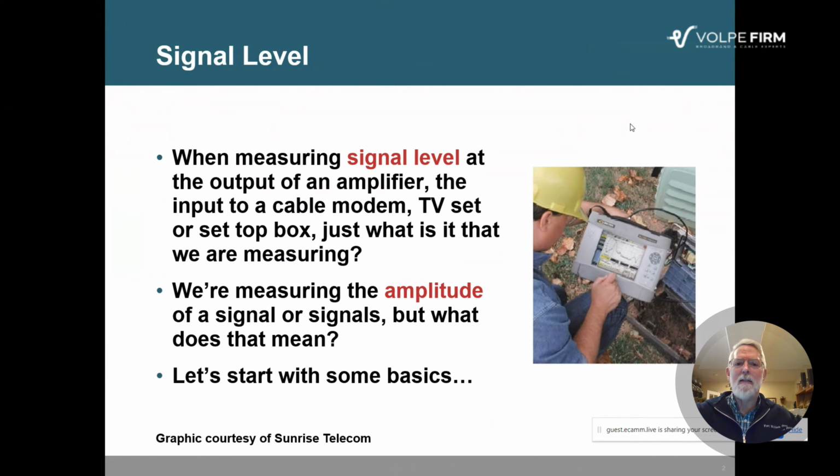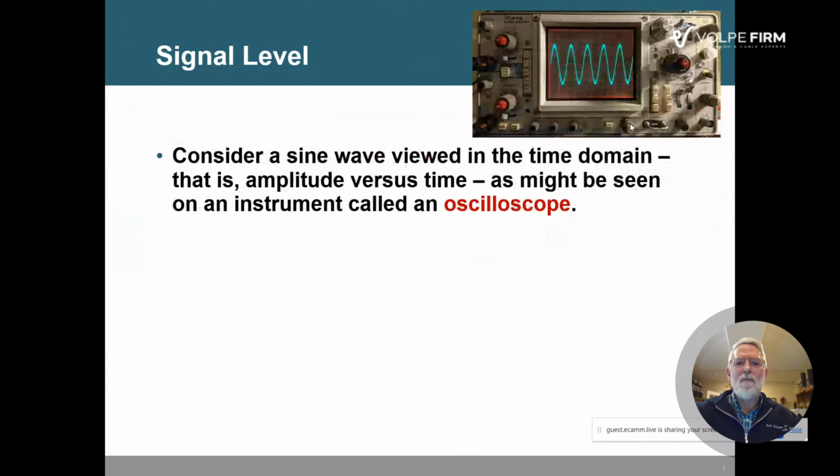And of course, keep in mind that it's even more helpful if you saw the presentation that we did last time on this program about the fundamentals of the decibel. So I want you to sit back and think for a moment of a different way to look at a signal from the time domain perspective. Some of you may have experienced using a piece of test equipment called an oscilloscope. This displays a signal or signals as amplitude versus time. A spectrum analyzer that most of us are familiar with displays signals in terms of the amplitude versus frequency.